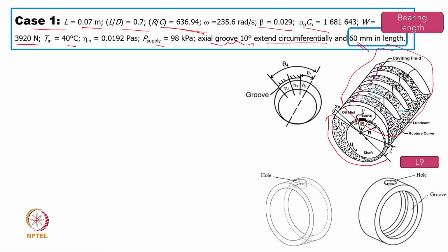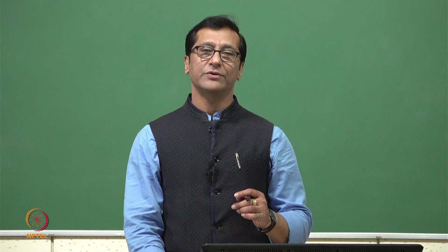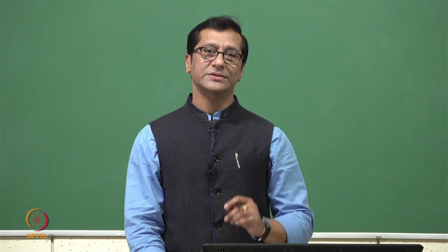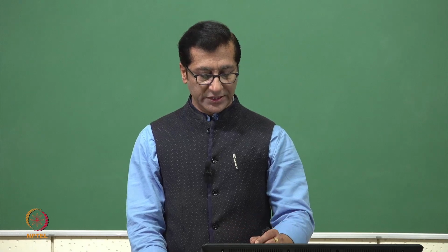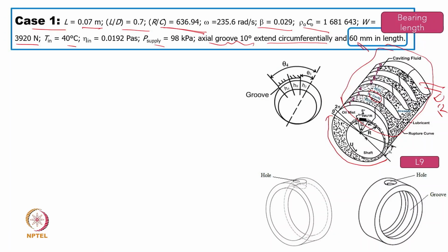But here, this is completely the divergent portion. In the divergent portion, the available liquid is not that much, and the liquid cannot sustain negative pressure. That's why there will be formation of air cavities and what we call liquid streamers. That is what will come out, and this is where we can feed the lubricant.